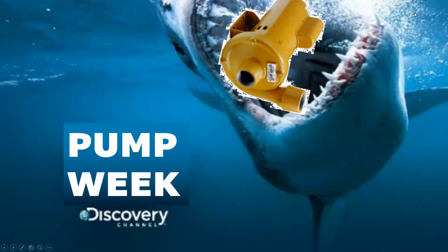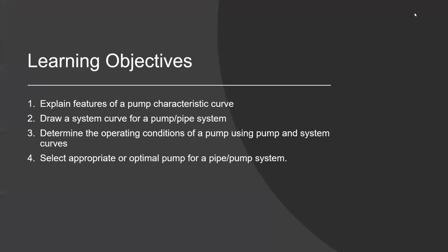Continuing our pump week, day 2 in pump week. Today we're going to explain features of a pump characteristic curve. That's what you all just generated in that activity. Pump curve, also known as a pump characteristic curve. We're going to draw a system curve for a pump and pipe system and calculate it. We'll determine the operating conditions of a pump using pump and system curves superimposed together. And then we're going to do an activity where we select an appropriate or optimal pump for a pump pipe system.